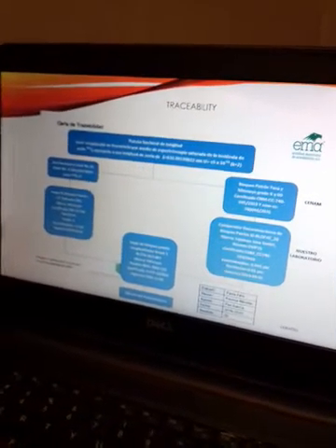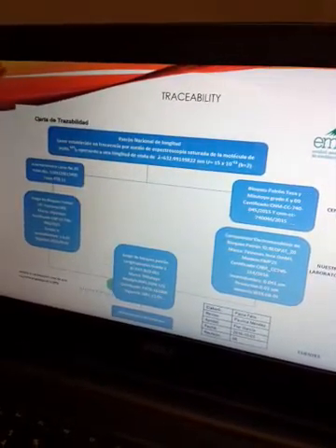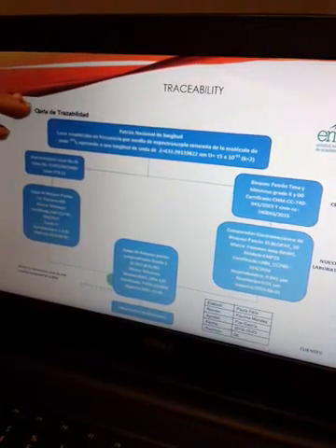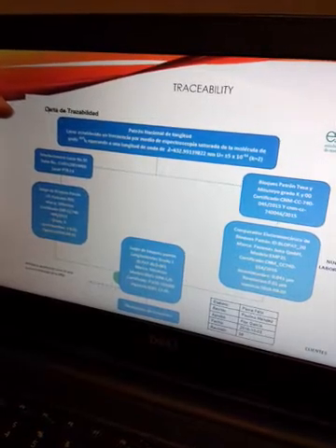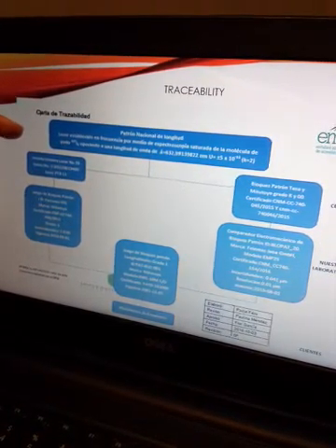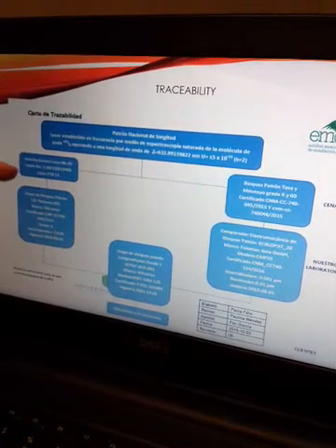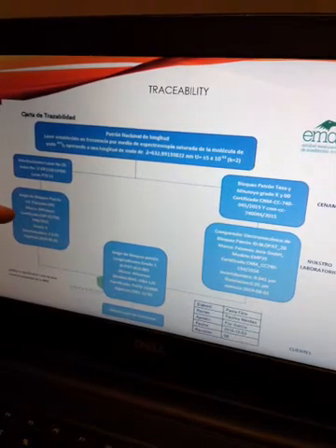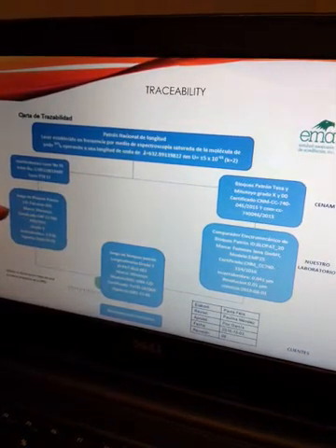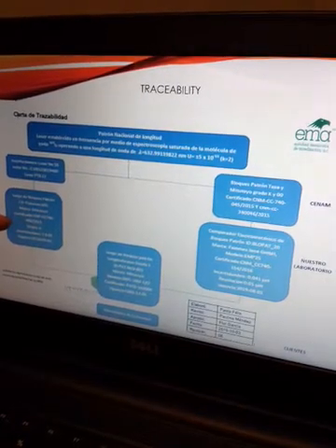So like I told you, we need to be sure that the instrument has traceability. We need to have a traceability letter that we receive from the laboratory we send the micrometer to calibrate.